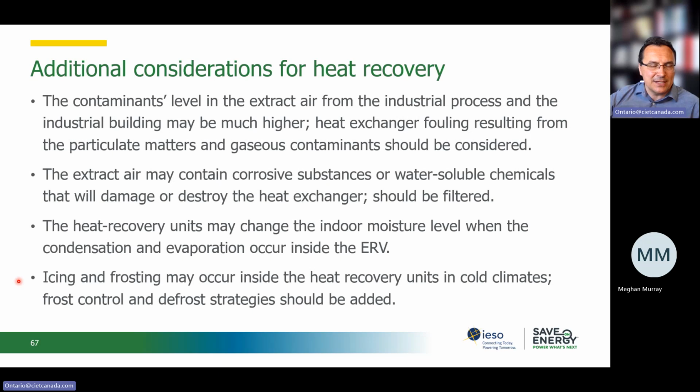So in colder climates, the exhaust air moisture can be condensing if we reach a dew point, or even freezing if we reach the freezing point, on the path of removing heat from the exhaust air to transfer it to the supply, to the fresh air.